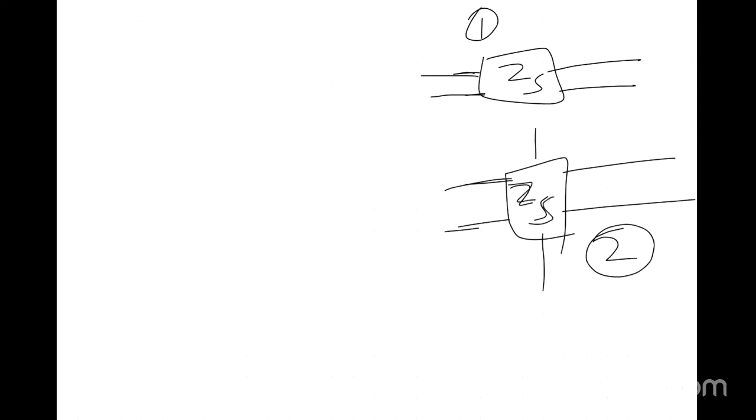Again, here also we are calculating V1, V2. Here also we are calculating four parameters. What are the four parameters we are calculating? The four parameters are S11, S12, S21, S22. And the input side I am treating as plus. Remember, this is a very important point. Input side is treated as plus. Output side is represented as minus.